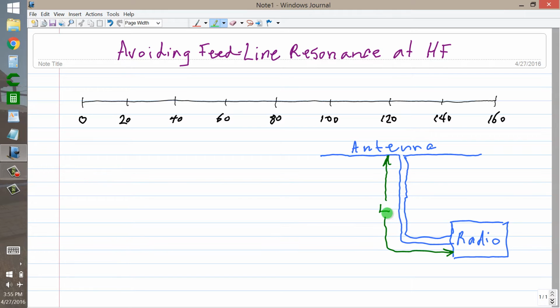What you want to avoid is any length of L that is a quarter wavelength or any integral multiple thereof, so that it is not quarter wavelength resonant or resonant on any harmonic thereof, so that it minimizes the possibility that this feed line will act as an antenna and develop what is known as antenna currents, which can cause that dreaded phenomenon, RF in the shack.